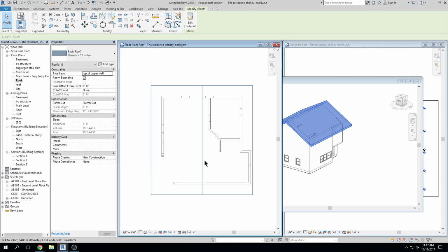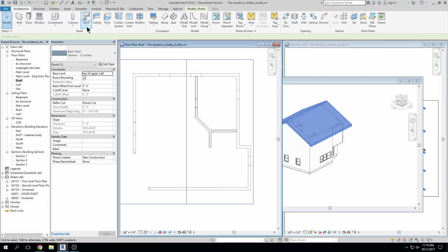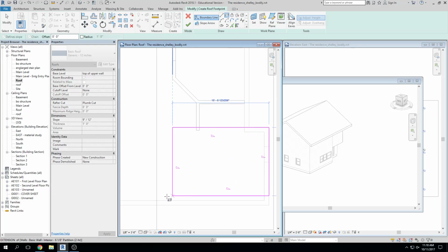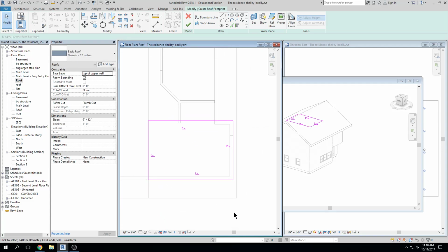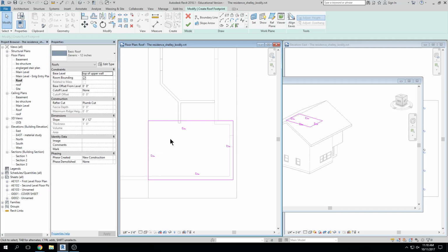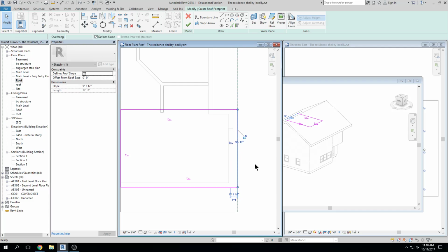Okay. So I'm going to create another little piece of roof that comes out as a dormerish type of piece of roof over the top of this architecture right here. So I come up here to architecture, I go to roof by footprint, and I'm going to draw the boundary of my roof. I'm going to keep it right on the walls for now. All right, so I want this to be a gable. I don't want that to slope. I want this to slope up, that to slope up, to create a little dormerish area. I'm going to bring this out to there.